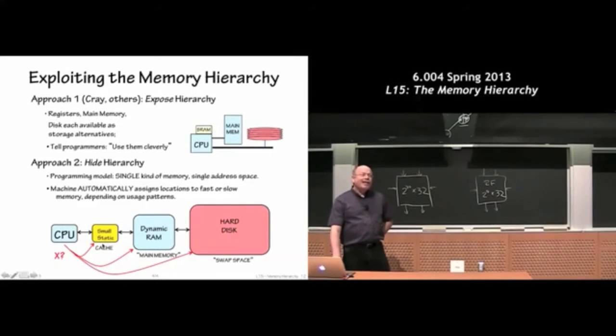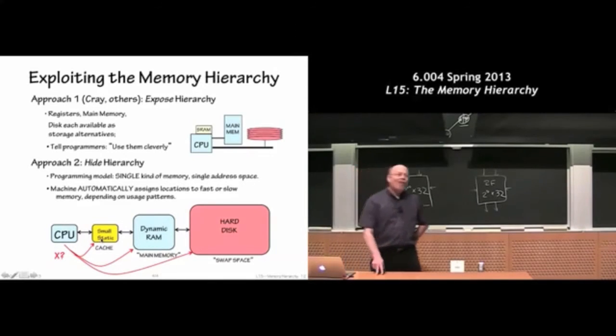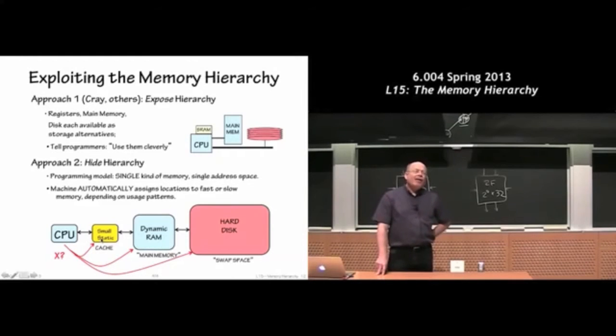So the size of the cache is important. To make your computer run faster, it's not so much that you have to make the CPU faster; you have to make sure that on average you're finding more and more information in the yellow box. The way we do that is by making the yellow box able to hold more and more bits. So the real key to performance in most modern systems is large amounts of cache.